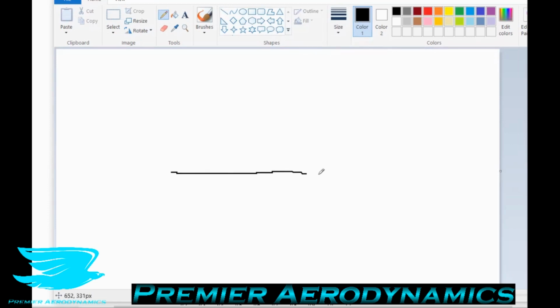So if we have a surface and we have an LSB forming over the top, we have a recirculation zone in here. Now, the bubble obviously increases the height of this object by a certain amount, and that often results in more wake at the back.